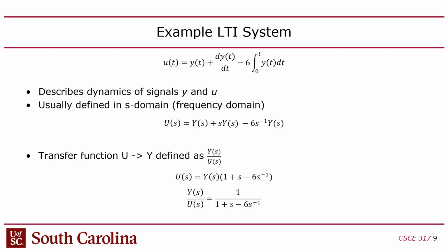And so that will give you this transfer function. Generally, when you do that, you want this ratio. Notice that there's only state variables on one side, and on the other side there's only s's, right? This is supposed to be a ratio of two polynomials. You generally want the denominator to be a polynomial where the lowest power of s is 0, so you'd multiply this thing by s over s to get it into the right form. You don't have to, and I didn't do it there, but anyway, you have this ratio.